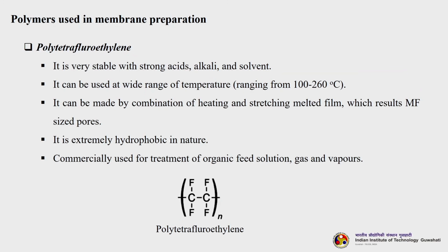The next class is PTFE, which is called polytetrafluoroethylene. It is also very stable with strong acids, alkalis and solvents. It can be used at a wide range of temperature. Usually, it can withstand up to 260 degree centigrade temperature. It can be made by a combination of heating and stretching melted film, which results in microfiltration sized pores. It is easy to fabricate also. It is extremely hydrophobic in nature. So, the adsorption of solutes due to its hydrophobic nature will be more, and it is commercially used for treatment of organic feed solution, gas and vapors.